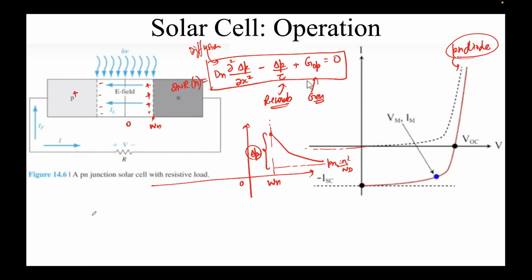total current, I have it here. No, I don't have it here. Sorry. So I have to write this. So the total current will be, let's say, I_PN, the pure PN junction, and I_light. The effect of PN as well as light. What is the current due to PN? We know the reverse saturation current, exponential q V_A by kT, minus 1. Here V_A is the applied potential.